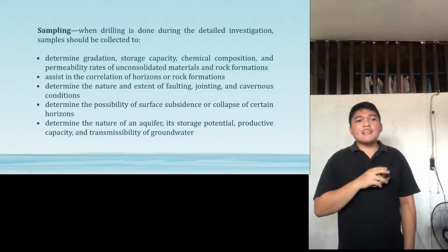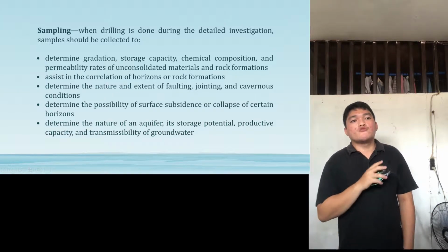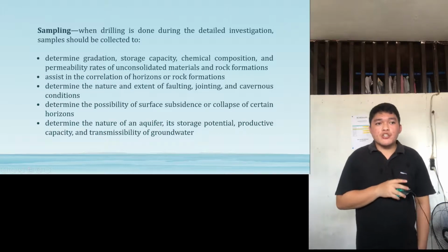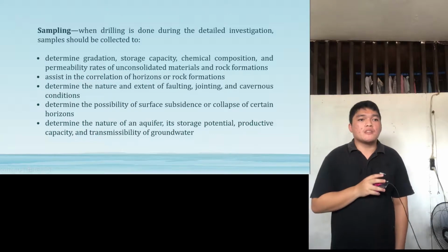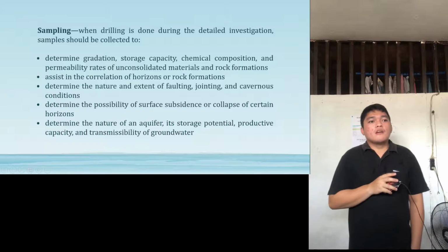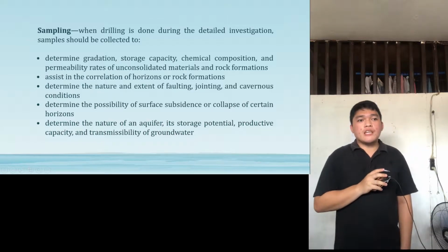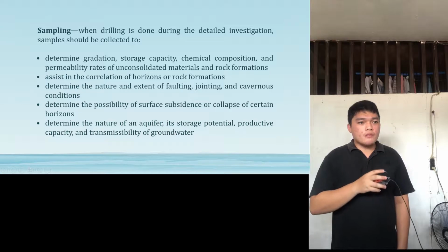Sampling. When drilling is done during the detailed investigation, samples should be collected to determine gradation, storage capacity, chemical composition, and permeability test of unconsolidated materials and rock formations. Next, assist in the correlations of horizons or rock formations.